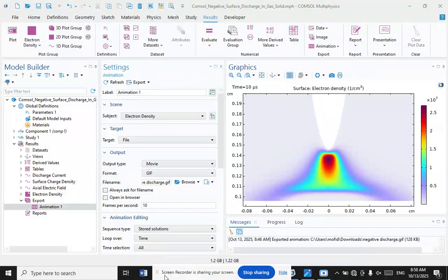grounded frame electrode. The system is moved using two driven wheels fixed at its extremities and is placed a few millimeters above the solar panel surface. The cleaning operation is done by moving the dust particles from the surface using the ionic wind coming out through a 5 mm wide opening located at the bottom of the device.